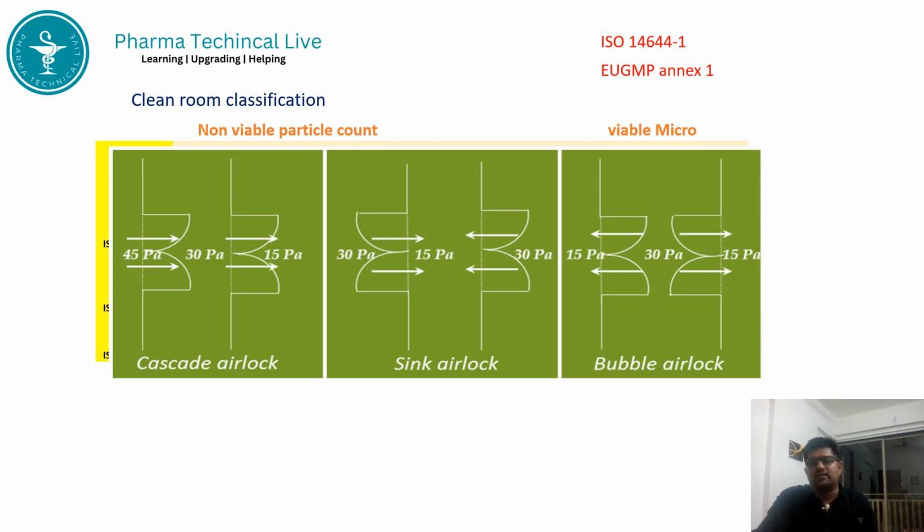In bubble airlock, clean air is flushed into the airlock and goes to the adjacent area. Like this, a double compartment airlock also keeps the area clean and helps maintain the cleanliness class. Also, an interlocking system on the doors has to be installed to maintain the airflow as designed and for effective functioning of the airlocks.